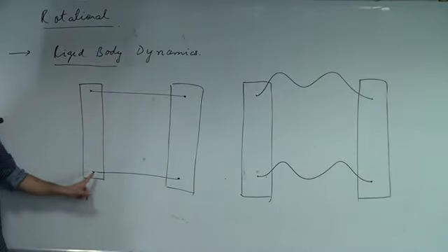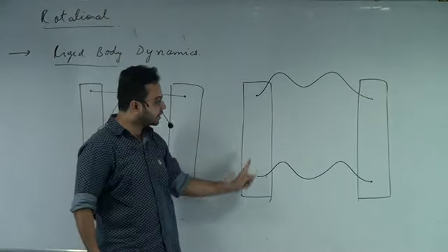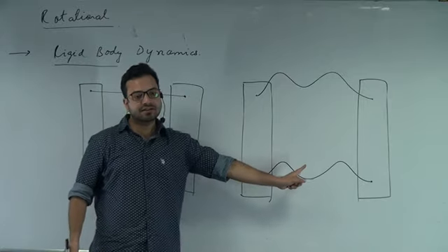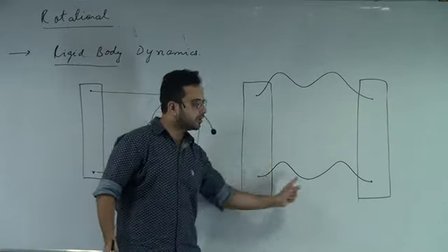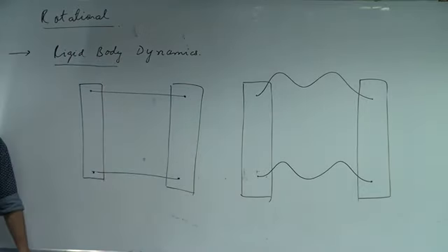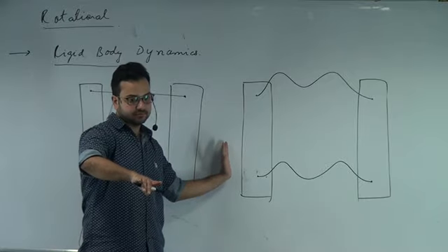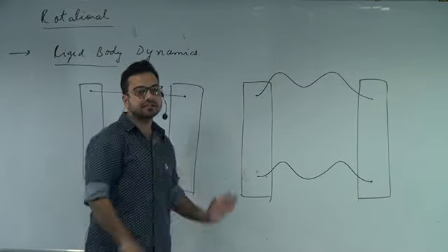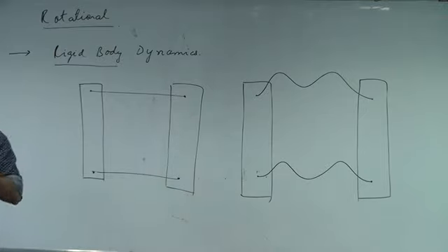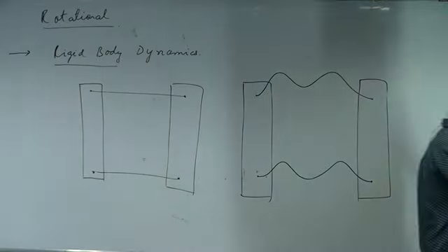So a point over here and a point over here is moving in a parallel trajectory. Right? The point here and the point here, is that moving in a parallel trajectory? Yes, this curve is parallel to this curve. So those 2 points are moving in a parallel trajectory. So this is translational motion. So this is translational linear. This is translational curvy linear. The path is curvy linear, but it is still translational. Is that clear? Okay, so that is translational motion.